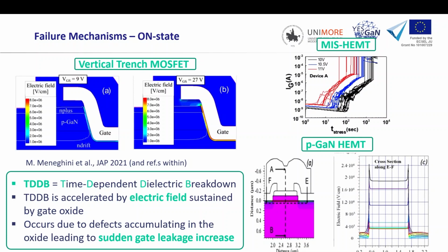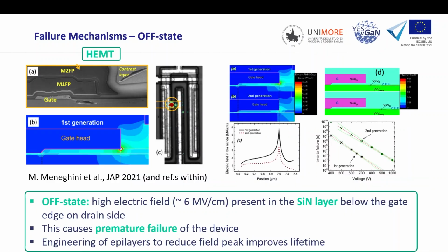In the p-GaN HEMT also, you have this region that is making your threshold positive, and you cannot apply too high a gate voltage, because you will start having a very high gate leakage that eventually will cause something very similar to this, that is taken on a MISHEMT. Though here you don't really have an insulator, you still have the problem of leakage after you turn this junction on. So this also needs to be taken into account.